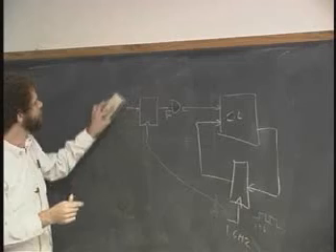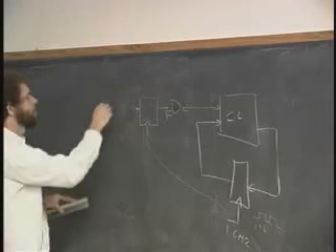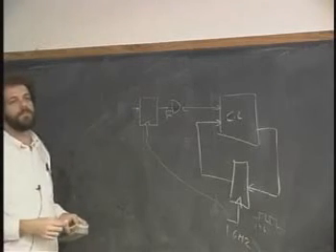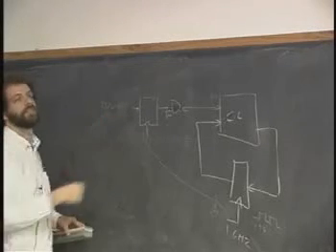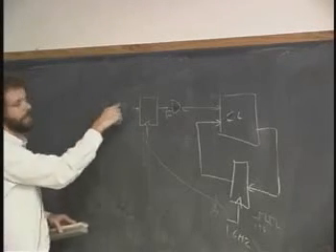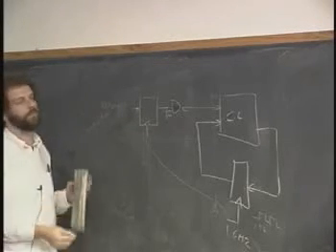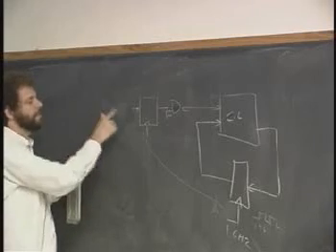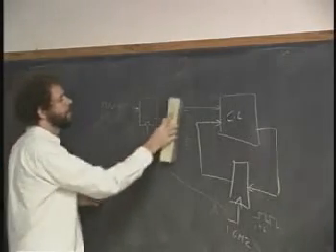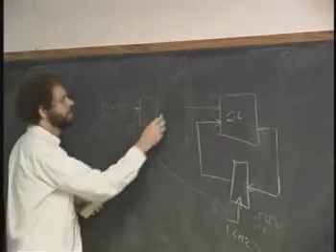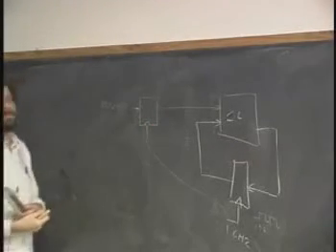But let's say that this isn't the Coke button, and we're actually getting a whole bunch of data in here. In fact, let's say we're getting data that's changing almost as fast as the clock. Let's say it's changing every 4 clock cycles. How are we going to deal with it? How do we synchronize this data to that clock? We can't wait around and not look at the output for that long. Other ideas?